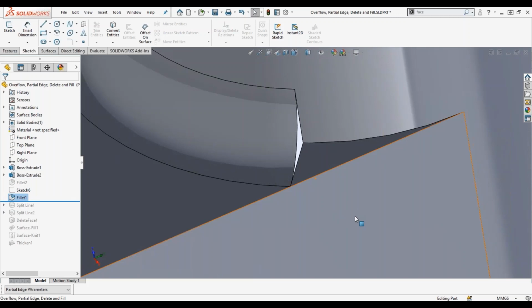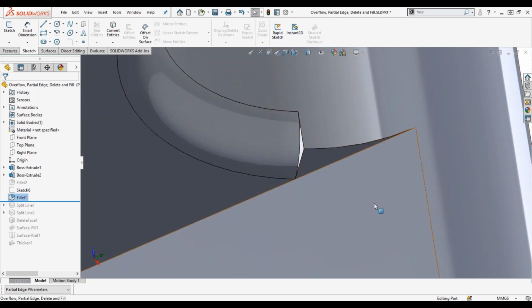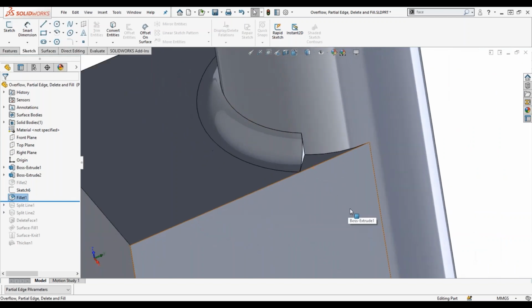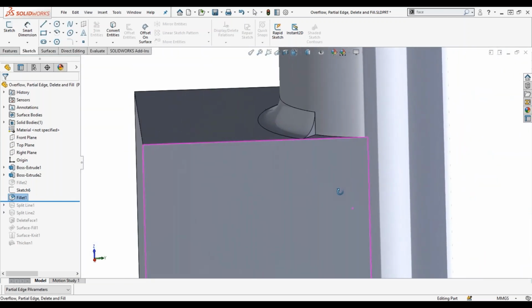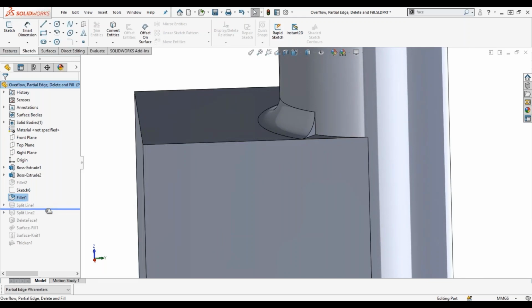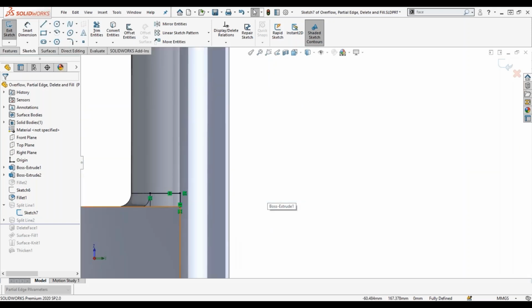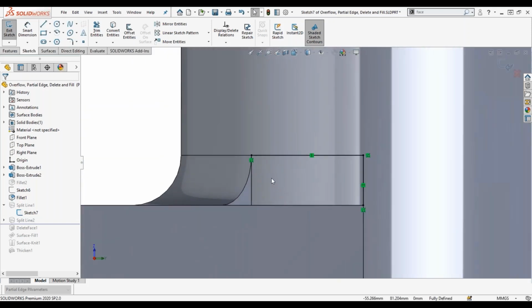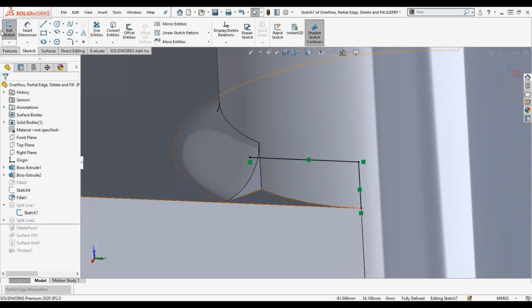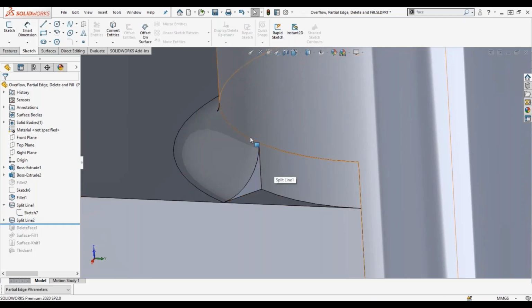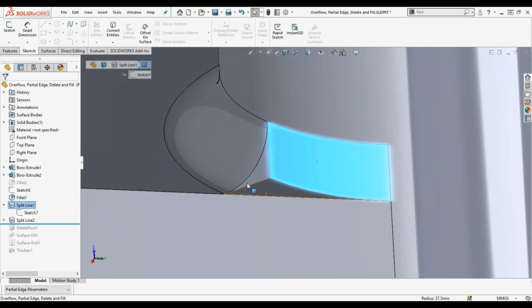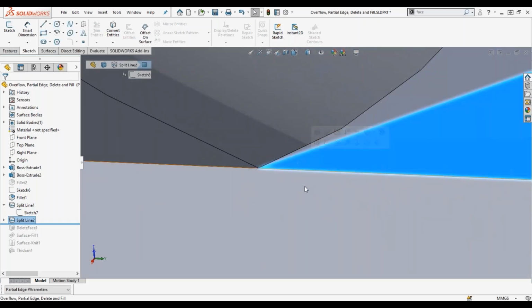And now what this is going to allow me to do is make easy patches to this area and fix up this area with some surface modeling. Again, I'm not going to go too much into the surface modeling, but these techniques are pretty easy to use, even if you've never done surfacing before. So the first thing that you would need to do is make those faces selectable. So I just drew on this plane 2 lines and then projected it onto this face, which then made that face selectable. And I did the same thing down here because it didn't quite reach the edge.